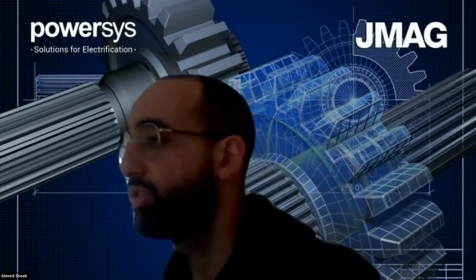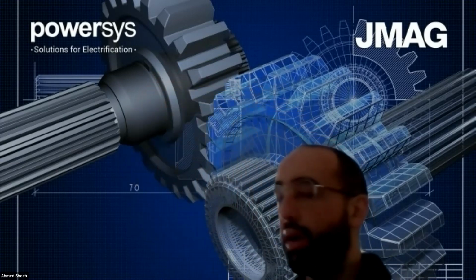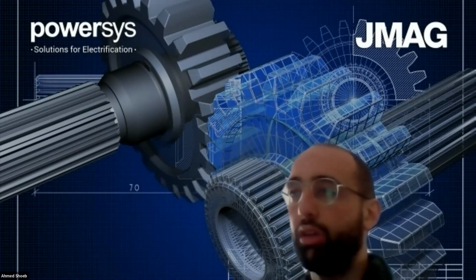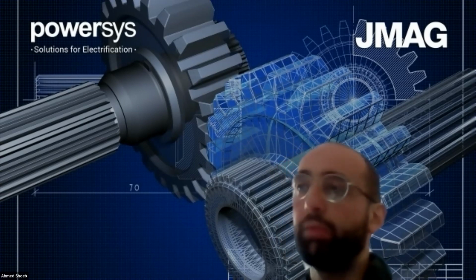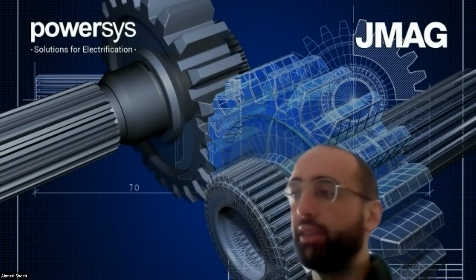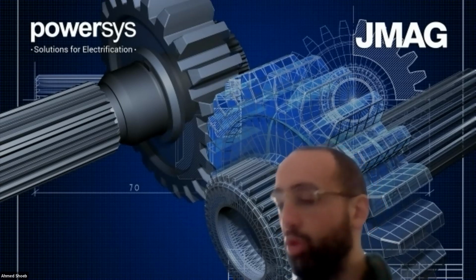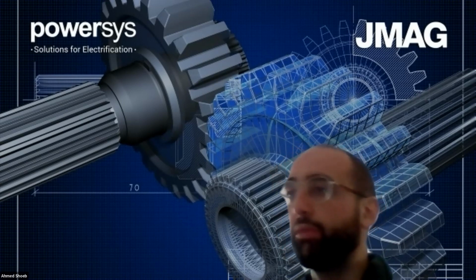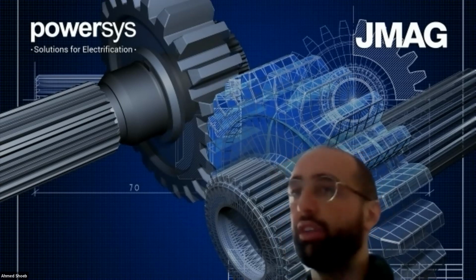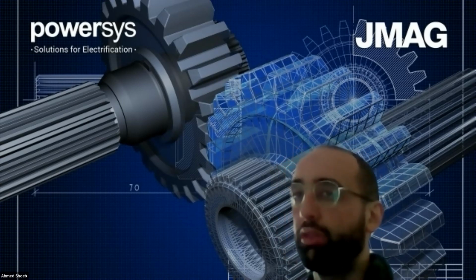If anybody has any question, but I can start, at least from my side. I have a question regarding the consideration of harmonic effects from the PWM drive. How would you handle such? Because usually when you're optimizing using a sine wave drive or a perfect case, an ideal current. So let's for argument's sake, you're optimizing for a sine wave drive, but you're not considering the PWM drive. So is that going to have an effect, and how would you handle that in the future?